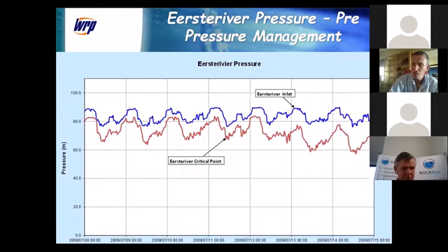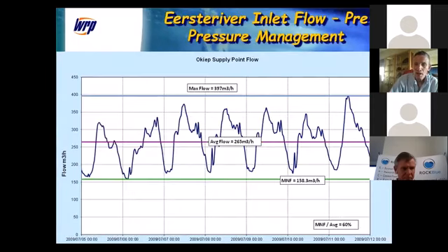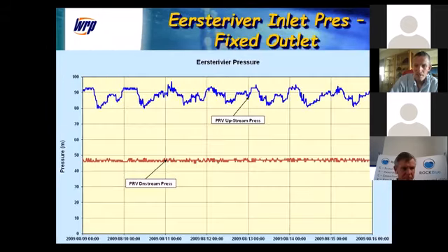This particular zone was perhaps a bit over-designed, and the pressure going into it was certainly very high. We had a minimum night flow originally in the zone of about 158 cubic meters per hour, which had a minimum night flow divided by average daily flow of 60%. So it was a very high leakage zone.